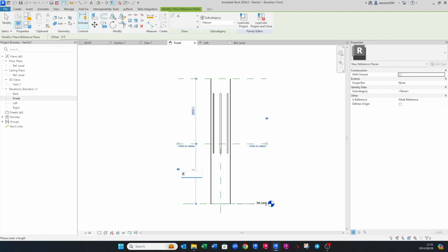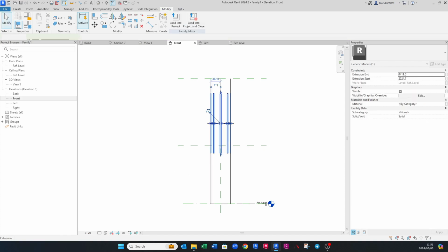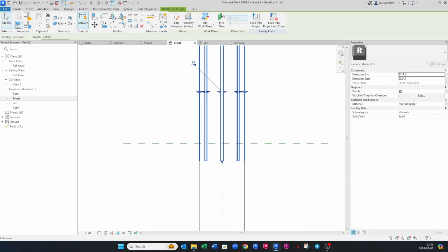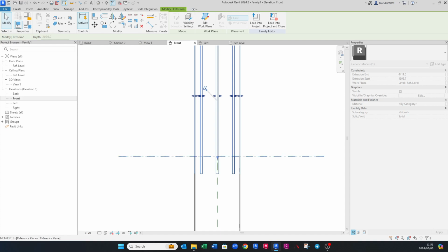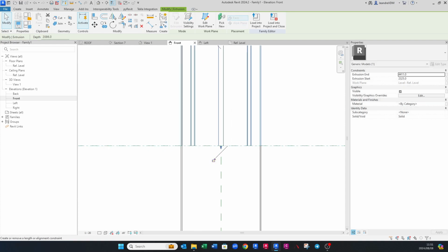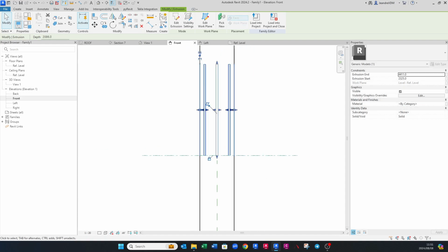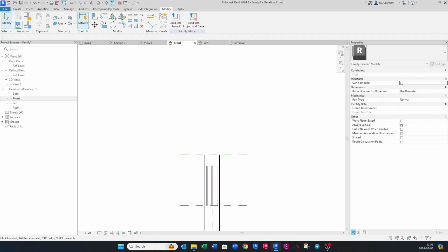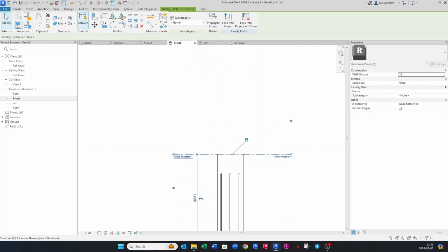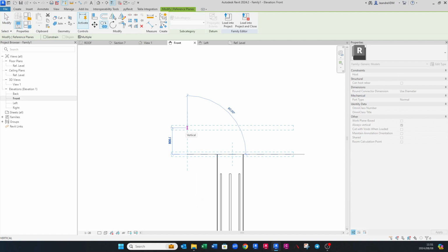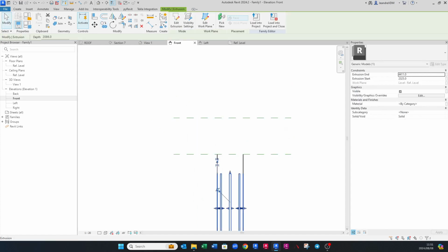So I'm going to make that 2350, or 2325 rather. That's just the level that the height of the cage actually starts. I'm going to pull this up, then it's going to ask me, do I want to lock it? And I'm going to say yes, I lock it. Then I want the cage to extend 1.1 meters beyond the level that I enter onto.